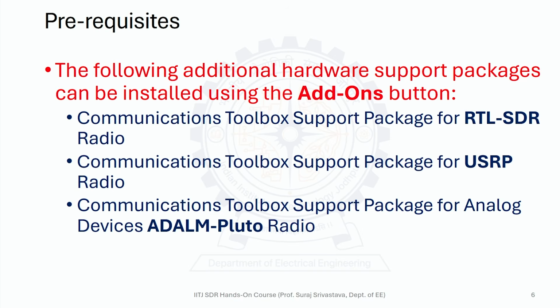And if you have the SDR with you, then toward the end of the installation, it will ask you to connect these SDRs. So you can connect those SDRs with your laptop or your desktop and then complete the installation, the device configuration. If you don't have the SDR, then you can simply skip that step. It will still allow you to add these blocks in your Simulink models and complete the design part. But you will not be able to run it on the hardware, because if you don't have SDR hardware, you will be just able to design the model.